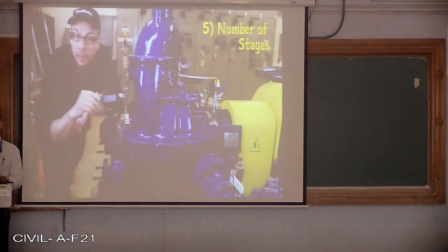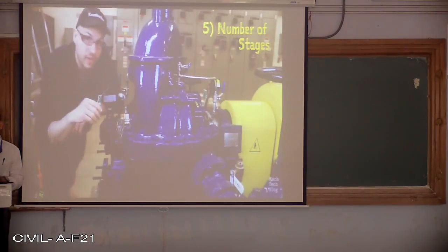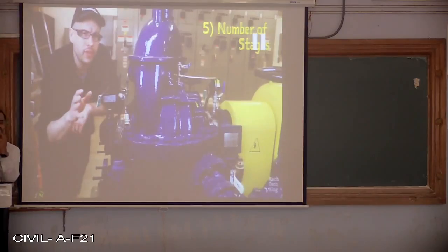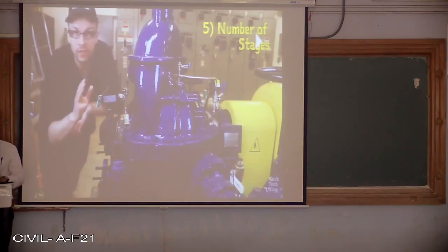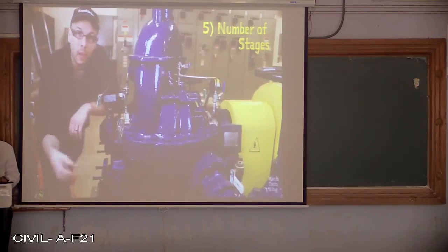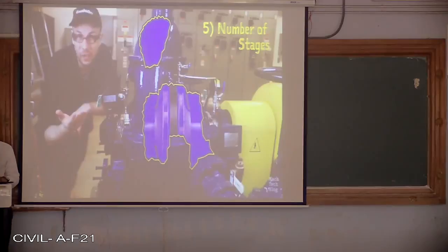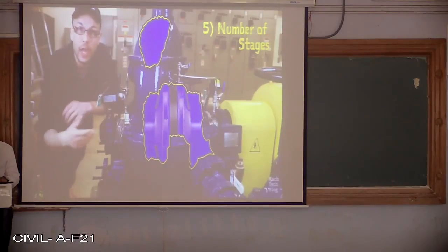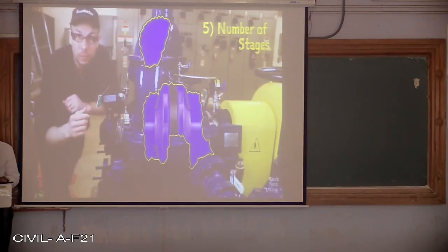Finally, a pump can be classified by how many stages it has. Most pumps... I would like to draw your attention here. This is a very important part as per our syllabus, so you can have a close look at it. Most pumps have one stage with a single impeller and a single volute chamber. However, some pumps have additional stages connected in series to help boost the pump's discharge pressure.